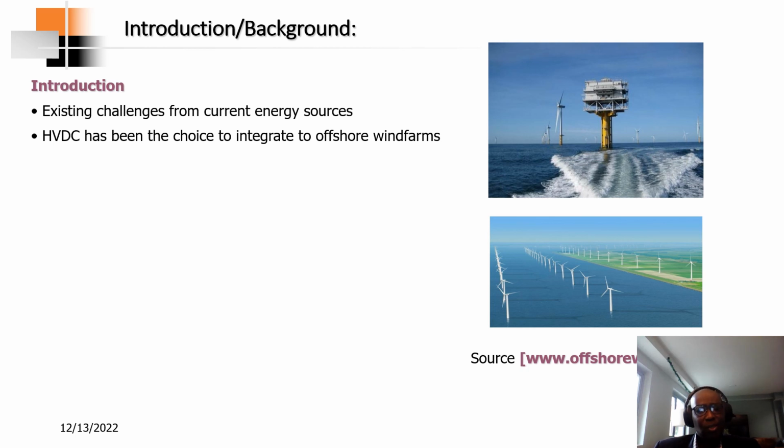Out of the technologies that can be integrated to these offshore wind farms, HVDC schemes can be integrated. But there's a limitation when an HVDC scheme is integrated to an offshore wind farm, and the limitation is a cable distance beyond 80 kilometers of submarine cable.